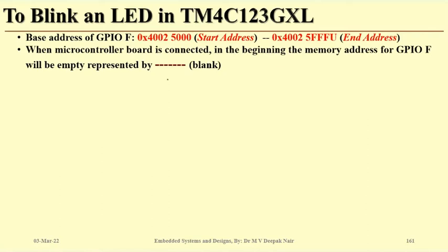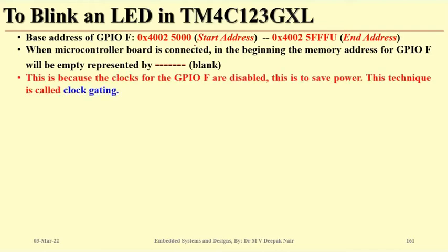I have shown you that when the board is just connected and you don't provide the clock, or when the clock is not enabled, the ports have this minus sign in the registers. So we need to get the clock gating done.